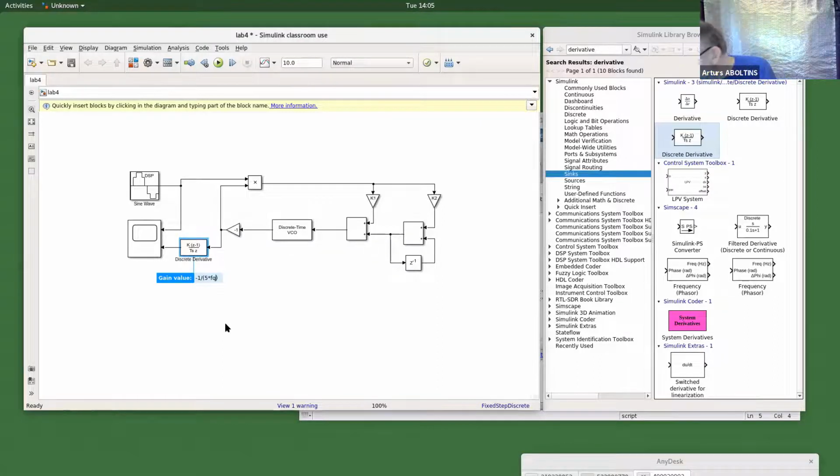But it could be necessary to adjust this a little bit to get the same amplitude, because the drawback with this derivative is that it doesn't only change the phase, it changes the amplitude, unfortunately, because this amplitude depends on the frequency as normal, and that's why we have to correct it by the gain value. And as I have seen that I still have something like 643 or something like this. Okay, let's put 6 or something. It will be anyway much closer to what is necessary.